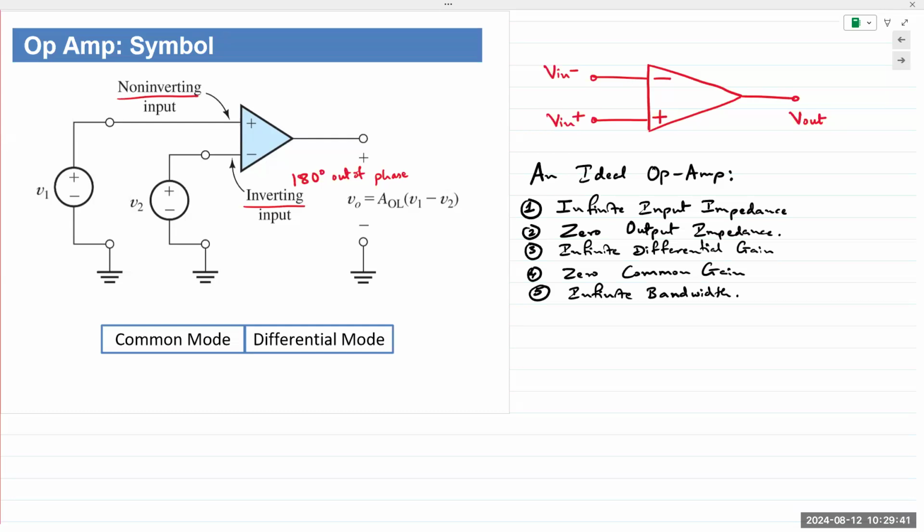You have an op-amp, it's catching all the signals that are surrounding that system. It will go into the negative as well as the positive input at the same time. So that noise signal will be common to both terminals. The property of the op-amp is that it will reject any common signals. So effectively, it rejects any and all noise signals. And that's the biggest advantage of having this kind of a differential amplifier.